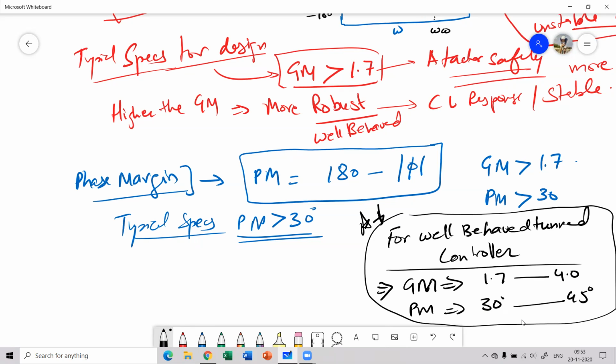जो गेन मार्जिन अगर 1.7 से कम होगा तो समवॉट अनस्टेबल होगा सिस्टम। नहीं, स्टेबल तो बच्चे होगा, बिकॉज इट्स सेइंग दैट गेन मार्जिन शुड बी ग्रेटर देन 1। अगर बहुत अच्छा ट्यून करना है हमने, तो वी नॉर्मली टेक इट टू बी इक्वल टू 1.7। 1.5 भी इट विल वर्क, 1.4 विल आल्सो वर्क, बट अगर 1.2 होगा, 1.1 होगा या 1 होगा, तो इट इज अपीयरिंग टू बी मोर टुवर्ड्स द अनस्टेबल साइड। तो एक स्टैंडर्ड डिफाइन है which says that it should be greater than 1.7। ओके, अभी एक्सप्लेन करूंगा अगर 1.7 हम लेते हैं तो क्या फर्क पड़ता है, और अगर 1.7 नहीं लेते तो क्या फर्क पड़ेगा। ठीक है,